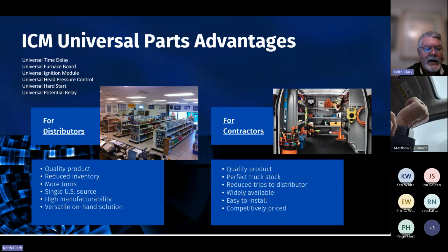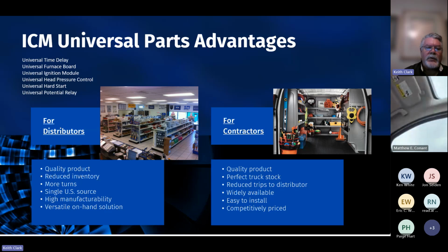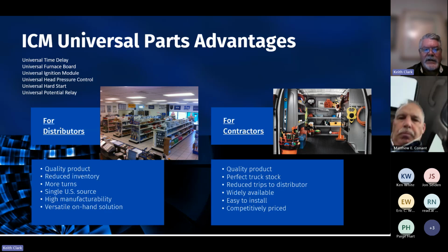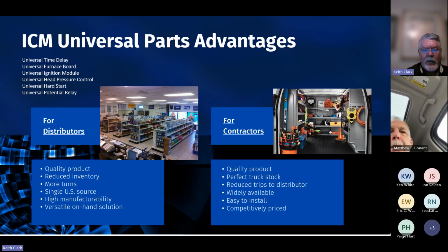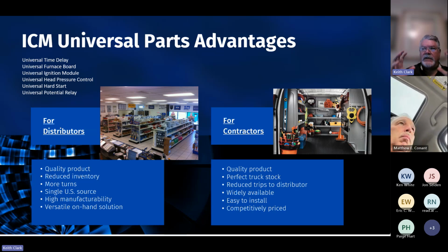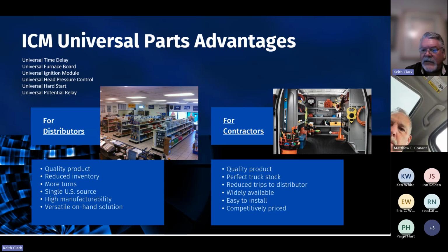Same with the time delay relay. And then universal hard start from 1/2 horse to 5 ton, which utilizes our universal potential relay on top of a capacitor. So it's universal, with differential voltage sensing, so it only stays engaged as long as is necessary, and then it drops out. So it's a great hard start and potential relay, because it's not going to just take the energy that's in the capacitor and dump that on the windings every time. It's only going to deliver what's necessary, and then once it senses that the motor has started, it drops out. So real brilliant technology.